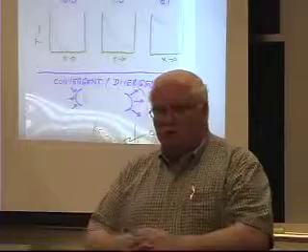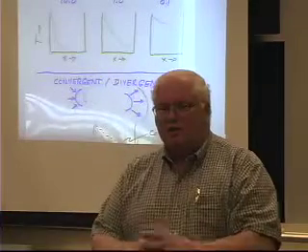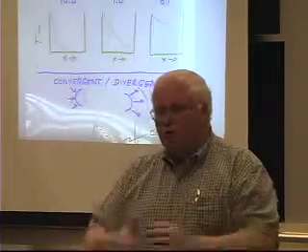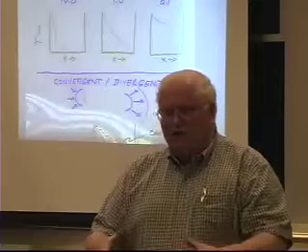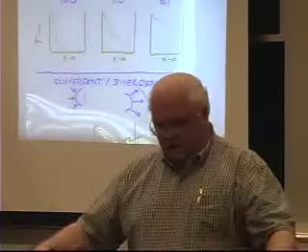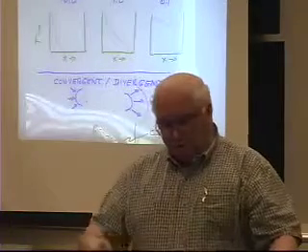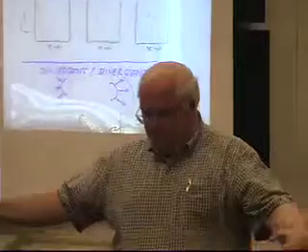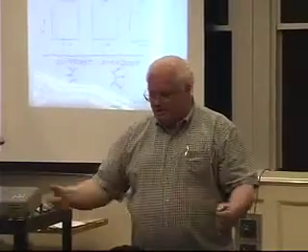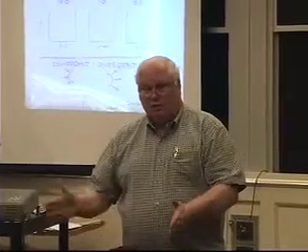They put it into a cold furnace. They didn't preheat the steel before they put it into a hot furnace, and because of residual stresses on a part that big. So what's the characteristic heat flow distance? Well, it's a cylinder being heated from the 12 o'clock position and the 9 o'clock position, so it's only the radius that's important, not the diameter. In that case, if it's 33 inches, the characteristic distance for heat flow is 16.5 inches. The radius, not the diameter.